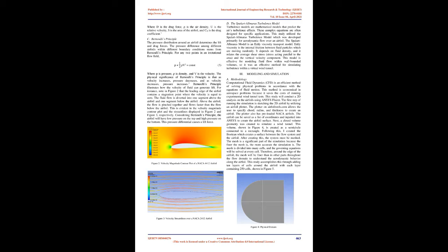Thus, the lift equation is, where L is the lifting force, ρ is the air density, U is the relative velocity, S is the planform area of the airfoil, and CL is the lift coefficient. Equation 1. Similarly, the drag force can be calculated by equation 2. D equals 1/2 ρ U² S CD, where D is the drag force, ρ is the air density, U is the relative velocity, S is the area of the airfoil, and CD is the drag coefficient.